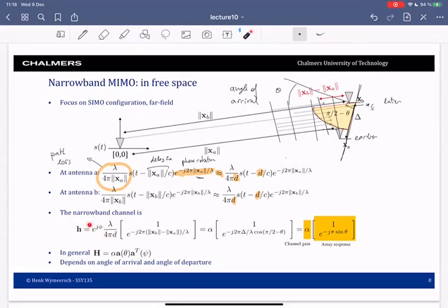And then I have a constant phase rotation, which I say corresponds to the phase of antenna 1. So then the remaining phase is 1. And then I reduce this phase from the second antenna. Okay, so I basically say that the first antenna is reference. This one has phase 0. Right, so this is equal to e to the power j0.